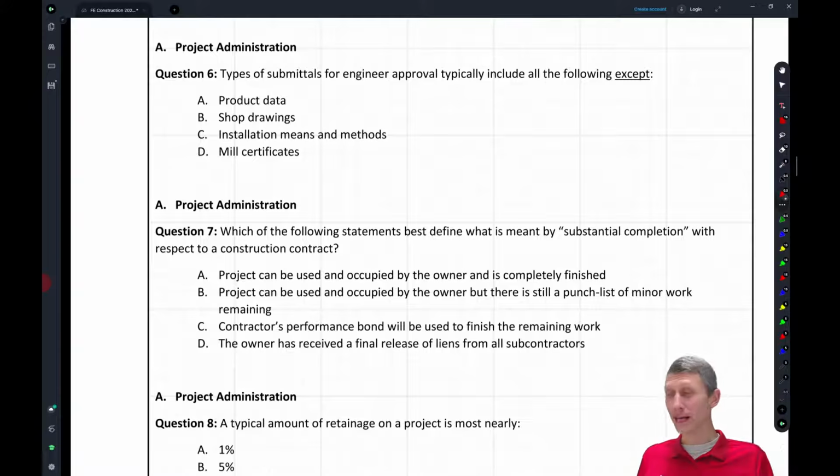Okay, a submittal is a piece of paper that gets sent in to the engineer that says, okay, you said you wanted PVC pipe that's SDR35. This is the pipe that we're going to use, the specific supplier. This is where we're getting it from. And here are the ASTM specs that make sure that it meets what you want for PVC pipe. So typically submittals are those pieces where the contractor takes a look at the drawings, talks to their supplier and gets the actual cut sheet of the actual product that